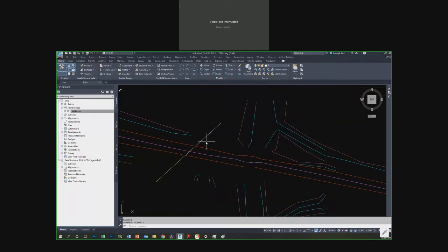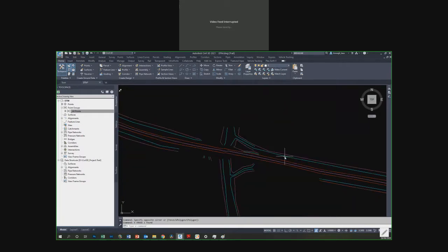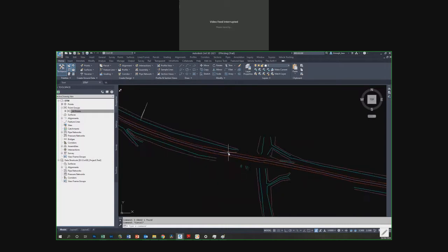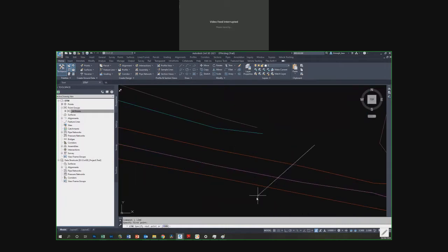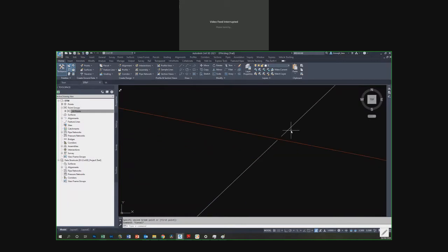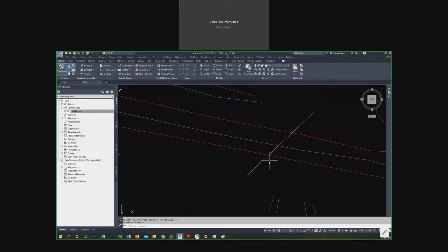So that's why it is recommended that none of your break lines should cross each other. Though we have an option in Civil 3D that we can use the intermediate value between these two levels, or an average value in between these two levels, but it is highly recommended that you remove all the crossings. Just break them, so that it will be simply like this one. Just break them on all the ends. That's the thing. So remove this part.